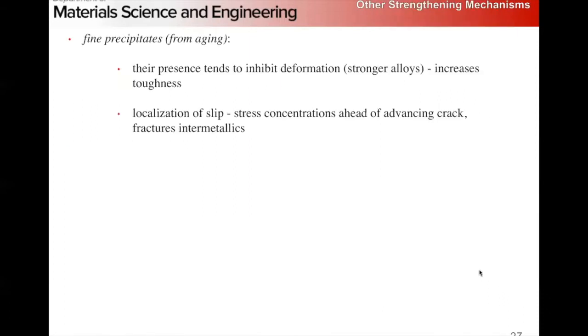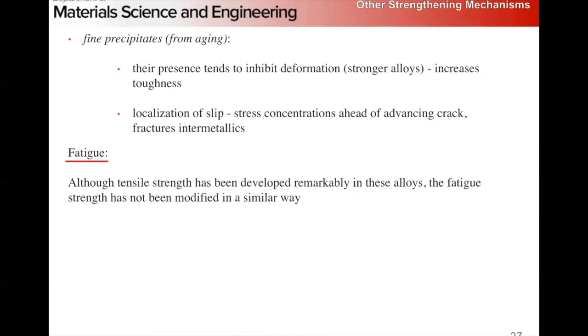Okay. Fine precipitates from aging: their presence tends to inhibit deformation and increases toughness, although they localize slip, right? Remember that as the particles are cut, that can give us stress concentrations in front of an advancing crack. Not a good thing, right?